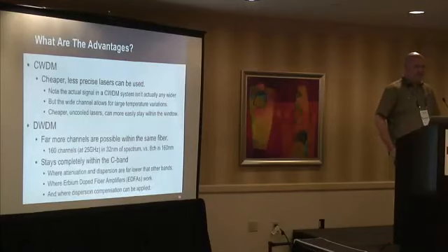The advantages, obviously, CWDM, it's cheaper. You need less precise lasers. You don't have to worry about the signal wandering. What actually happens is not that the signal itself is any wider, it's that it's free to move about. You don't have to have as precisely manufactured lasers. You don't have to have the cooling be quite as nice. You've got a pretty big window that you can send your signal in.